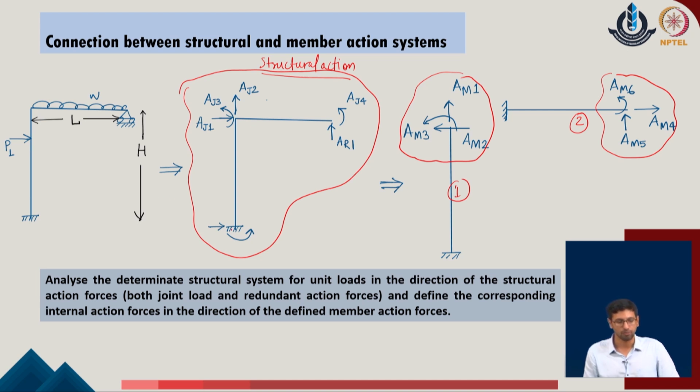So, in order to do so, we can analyze the determinate system, because these are all the determinate systems of the given problem. We can analyze this determinate system for the unit load in the direction of the structural action forces. I can apply the unit load corresponding to the individual joint action forces on the given system, and with respect to each of these structural action forces, including both the joint loads as well as the action because of the redundant part, we define the corresponding values of the forces in the direction of these member forces.